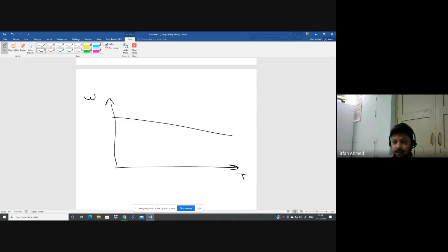Okay, so once again, I've drawn the speed torque characteristic under rated voltage, rated flux, and without any external resistance. Now, I want to increase speed above the rated speed. We've already seen that this is not possible by increasing the voltage because we are already at rated voltage. So the next option is we can change the flux.